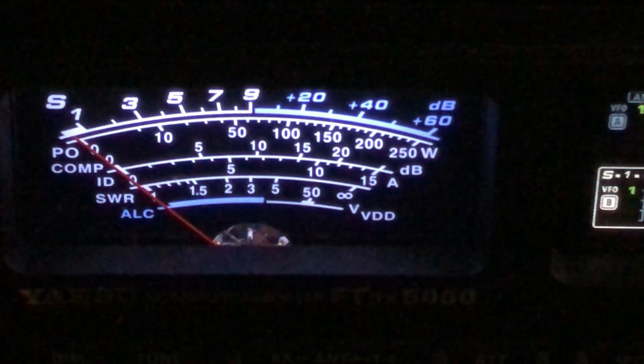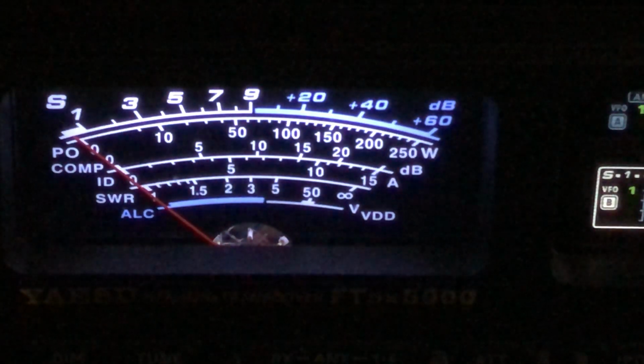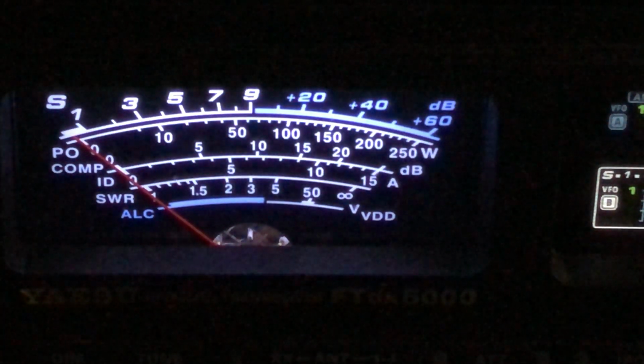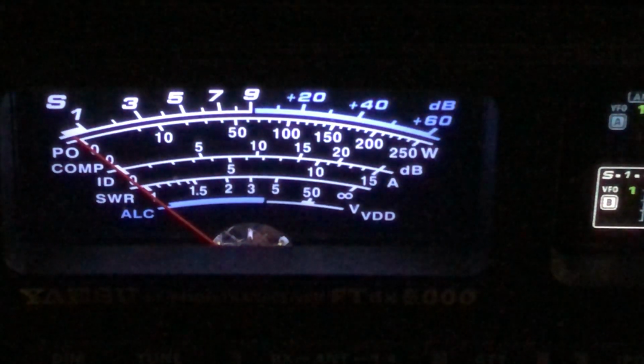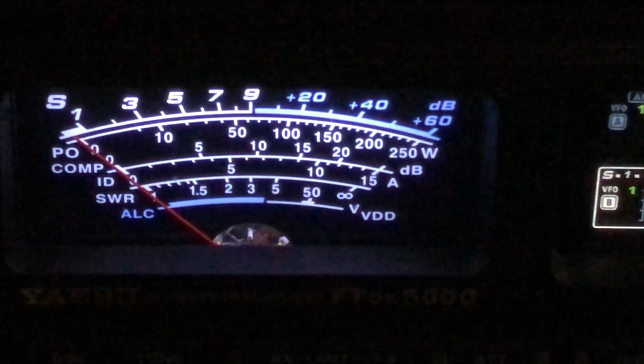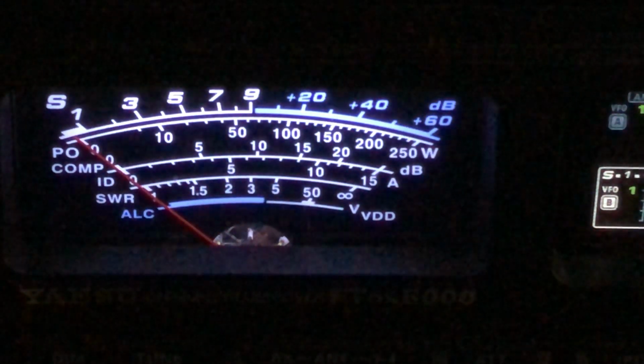So with these meters, it's a tough thing for the manufacturers to get this perfectly accurate by spacing those little lines out, anticipating how that needle is going to move. It's called a D'Arsonval movement. That's a real needle with a little spring in there.